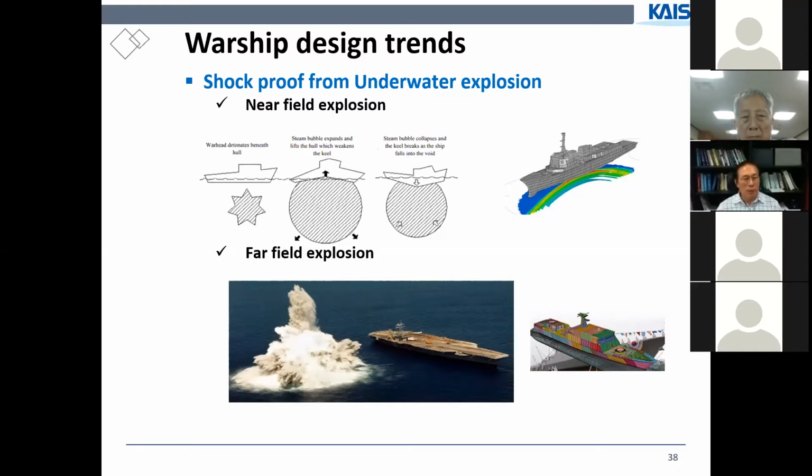But far-field explosion is like this: this is our ship, and this is some enemy attack underwater explosion, for example, mines or depth charges like that. The far-field explosion is the effect of the shock to the ship. Normally, the whole structure is safe, but the onboard equipment is badly damaged.